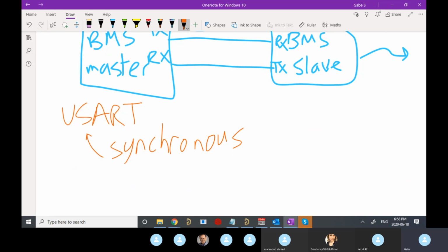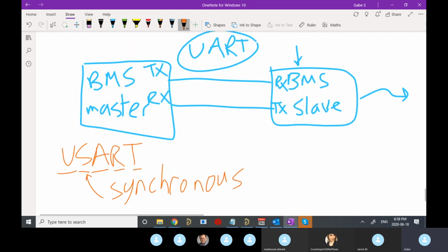I don't understand why you'd use this over SPI, but it's kind of dumb how they named it because it's universal, synchronous, and then they say asynchronous next, and then receiver transmitter. So all you do is you add a clock, CLK. So that clock gives you some synchronizing capabilities, so you don't have to match baud rates anymore. But yeah, not super common. But you'll often see it in microcontrollers. Like you can use some of the pins as USART/UART. But I usually use UART.